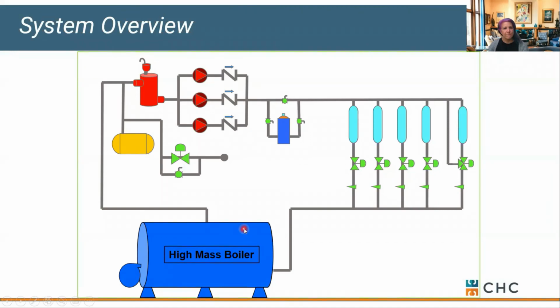My expansion tank, when am I going to troubleshoot that? Well, if I'm having pressure fluctuations in my system, or my boiler is popping a relief valve, or I'm making up a lot of water into my system, pretty good indication that I'm sending it down the drain somewhere. And that's probably due to a faulty expansion tank. Either it's failed or ruptured, or my air charge isn't correct, or somebody has valved it off.